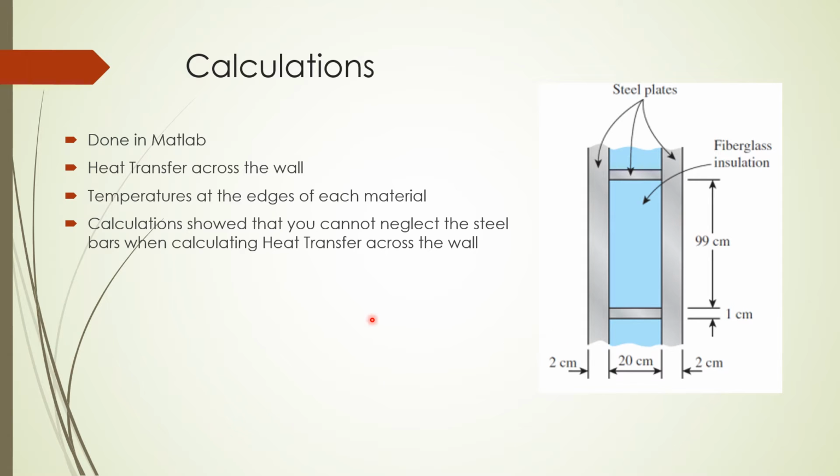For our calculations, they were done in MATLAB, and that's where we got all of our numbers, and that's where all our calculations were done. Calculated the heat transfer across the wall, temperatures at the edges, and then we did a calculation to prove that you could not neglect the steel bars when calculating heat transfer across the wall.